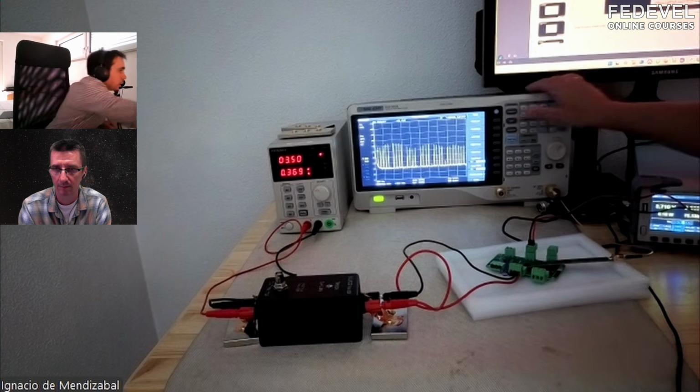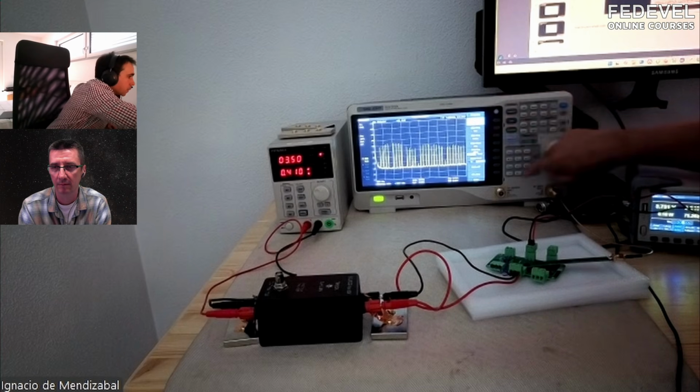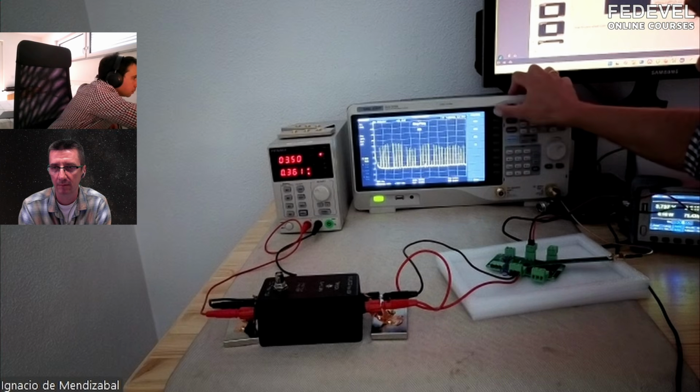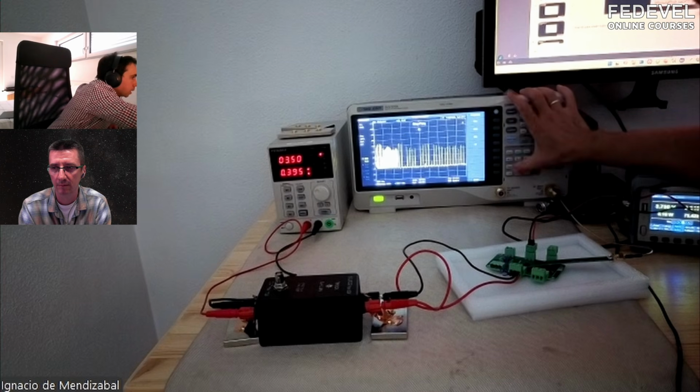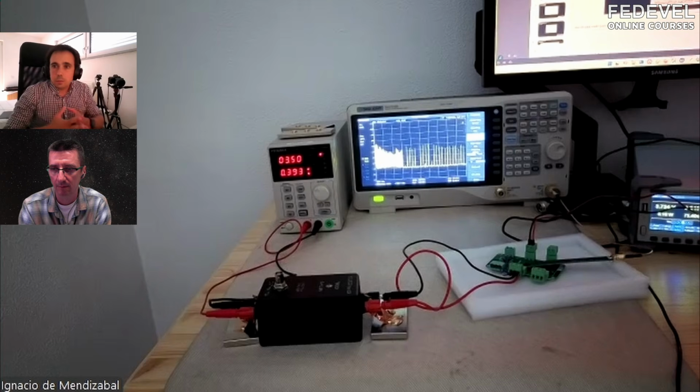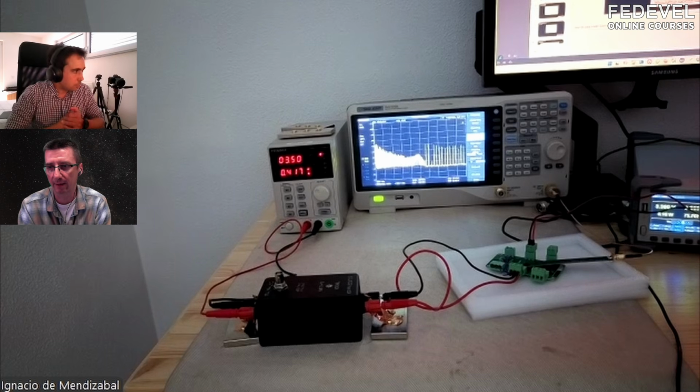Because you see that the signals are going. So imagine that I am at 200 mega, and imagine that here I am at 500 mega. It's going to take some time, but we will see that there are a lot of signals there. So you can have the same signal frequency, but if the rise time is very fast, the bandwidth that the signal will occupy will be much higher. That's exactly what is seen between sinus and square measurement.